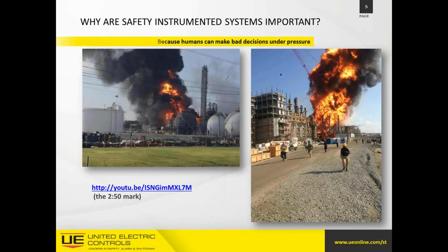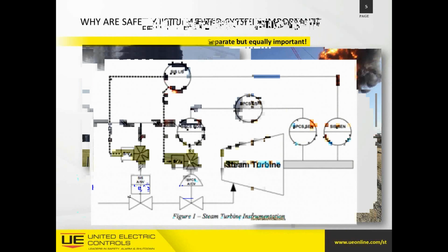There are really two driving standards, if you would, that drive the whole practice of safety instrumented systems. When properly designed, they would be built around an international electric code, an international standard called 61511. And then there are also some internal standards that are proven-in-use type standards. So there are two that exist, and then of course you may have heard S84 before, but I think we're going to focus in today on IEC 61511 as our driving standard for safety instrumented systems.